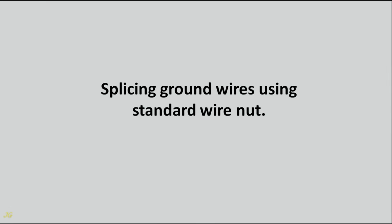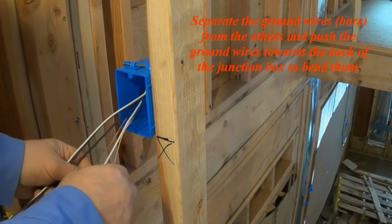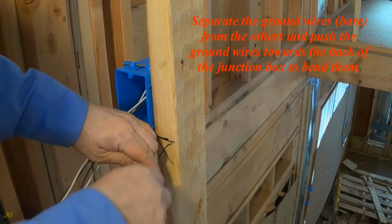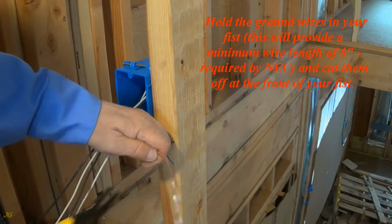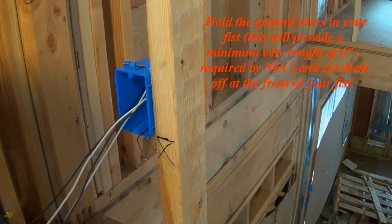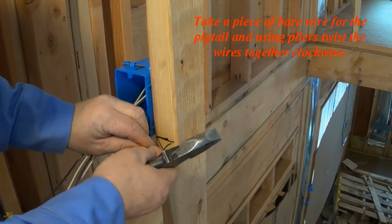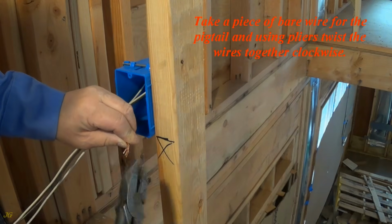Splicing ground wires using standard wire nut. Separate the ground wires, bare, from the others and push the ground wires towards the back of the junction box to bend them. Hold the ground wires in your fist. This will provide a minimum wire length of 6 inches required by NEC, and cut them off at the front of your fist. Take a piece of bare wire for the pigtail and using pliers twist the wires together clockwise.